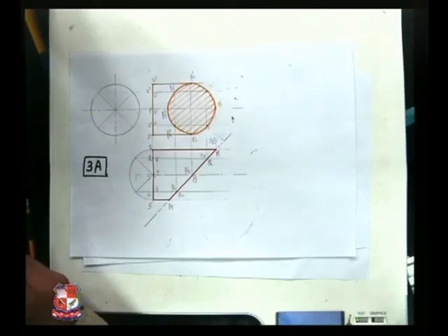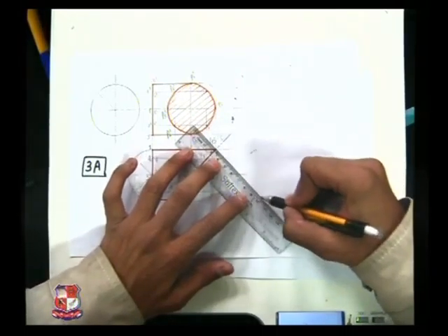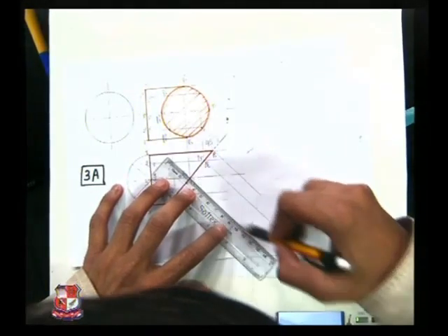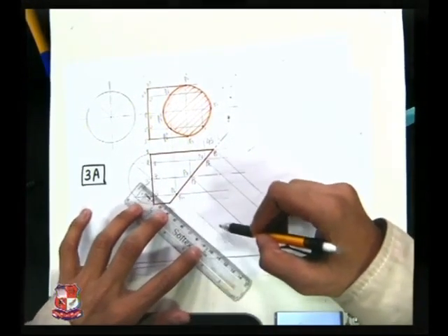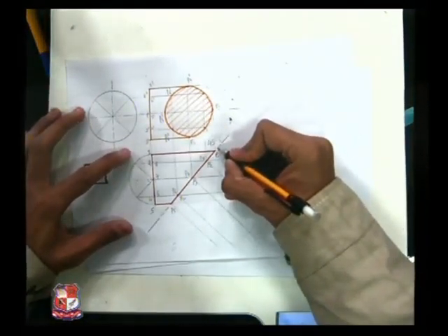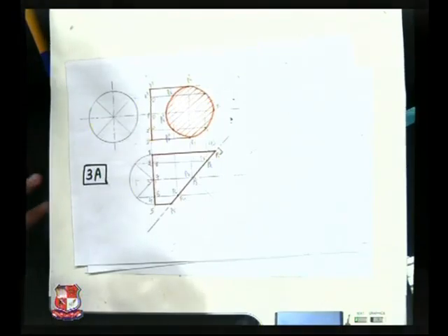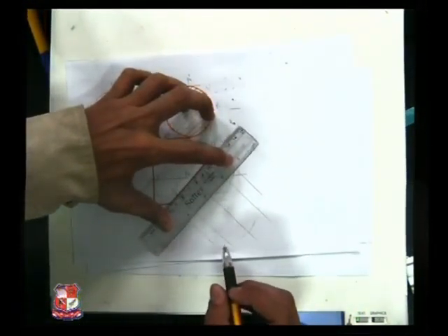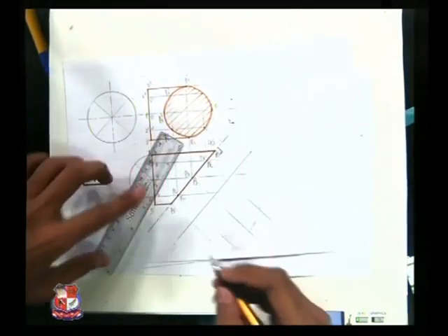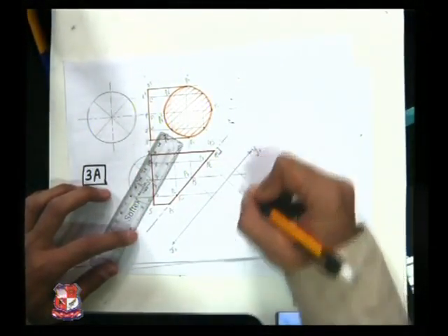For that we take projection from this P1, P2, P3 like this. Draw straight vertical lines from all these points, P1, P2, P3, P4, P5 and P6, P7 and P8. This line should be drawn in such a way that it becomes a right angle to this reference line. This angle should be 90 degrees. And draw a line at any distance parallel to this cutting plane line. This is called the auxiliary plane line, that is X1 and Y1.